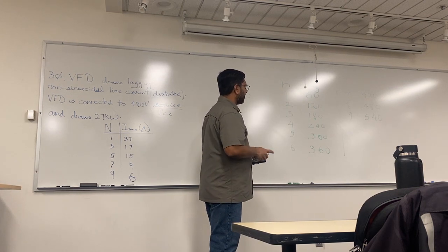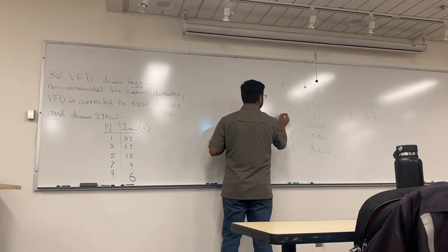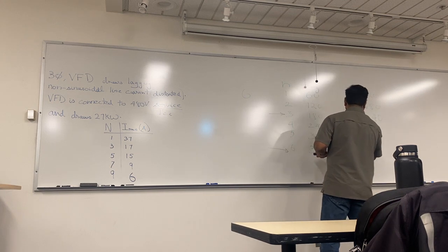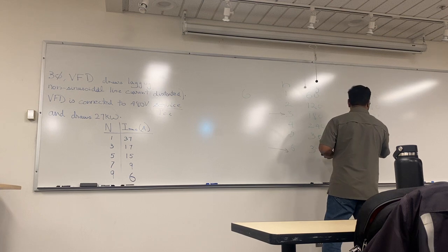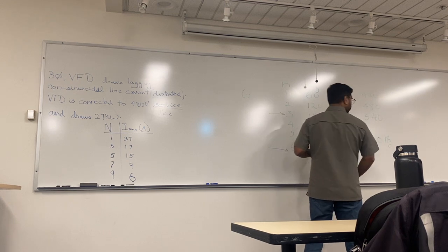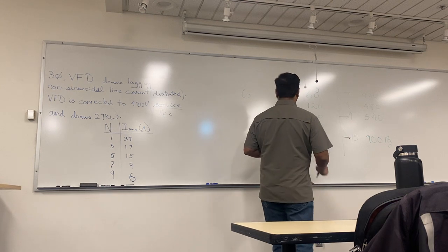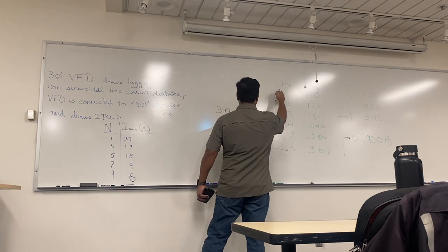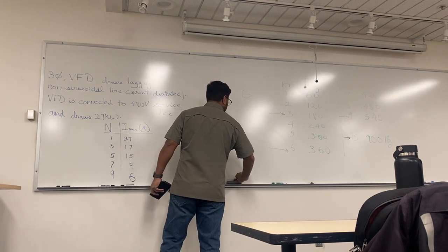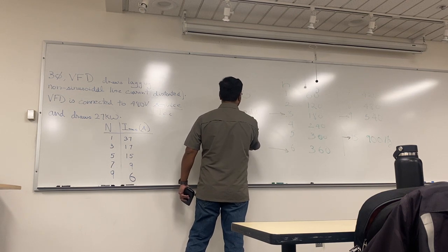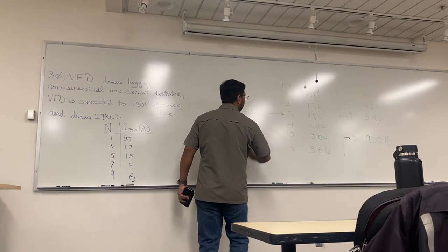So for the purpose of harmonics, and that too just for a three-phase, keep that in mind. These are the ones that are going to cause you an issue. 3, 6, 9, and then of course 15. That's 900. Is it 900? Yeah. Not 3, 6, 9, not 12? Not 12, and the reason for that is, what you need to do is 3 times h. You keep in mind that it has to be 3 times an h, and it has to be an odd number. So no 6. Okay. 3, 9, 15, no 12.